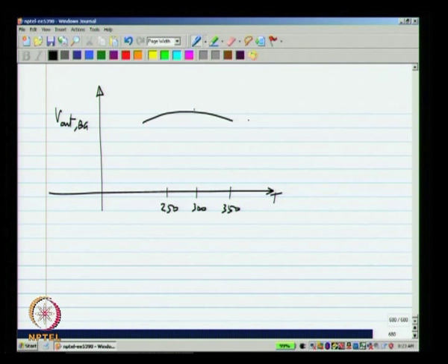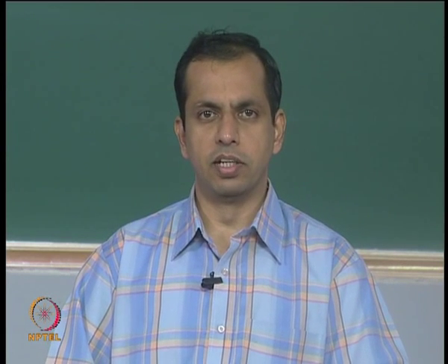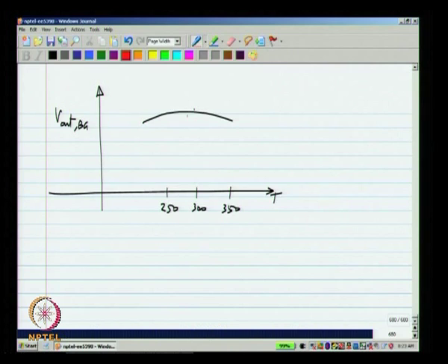Now, just like we added the positive and negative temperature coefficients, the proportional to absolute temperature voltage and the base emitter voltage, we can also try and correct the curvature of this temperature dependence. For that, you will generate currents which have the opposite kind of temperature dependence by using an appropriate combination of PTAT currents and constant currents and perhaps temperature coefficients of resistors. And if you add to this a small voltage which has the opposite temperature coefficient, then the resulting voltage would be more constant.